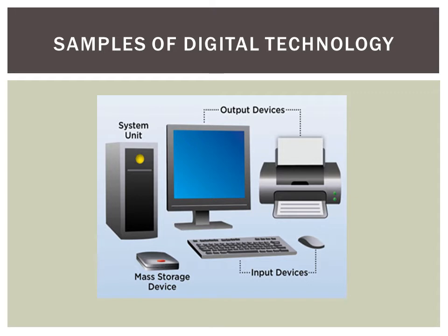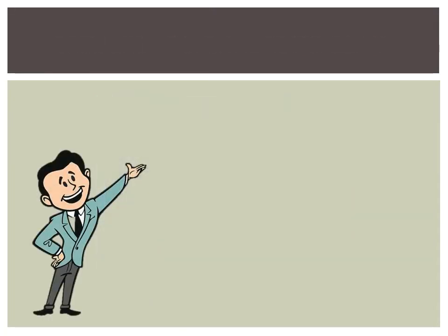An increasing majority of applications in electronics, as well as in most other technologies, use digital techniques to perform operations that were once performed using analog methods. Here are the chief reasons for the shift to digital technology. Number 1. Digital systems are generally easier to design. The circuits used in digital systems are switching circuits, where exact values of voltage or current are not important, only the range in which they fall.